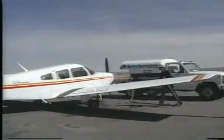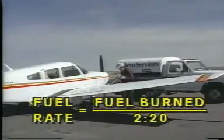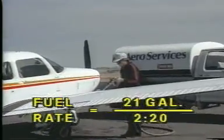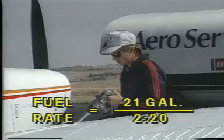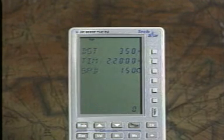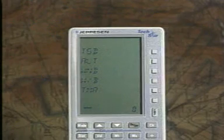Fuel problems can also be solved in this mode. For example, after you landed, you had your plane refueled and found out you had used 21 gallons of fuel. What was your actual rate of fuel consumed per hour? You could solve this problem using the secondary compute function of this computer, which will be discussed later. But for now, let's go back to the main menu by pressing the Mode key.